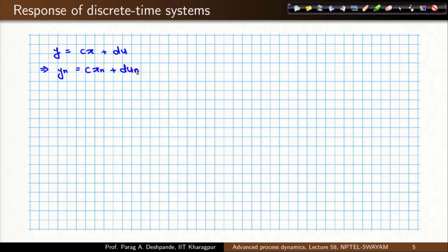Which means to determine the value of the output variable at a given instant of time, you need the value of the forcing function as well as the dynamical variable at that instant. Since we have a SISO system, single input single output, can we devise a method such that I need to feed only the input variable and I get the output variable directly?